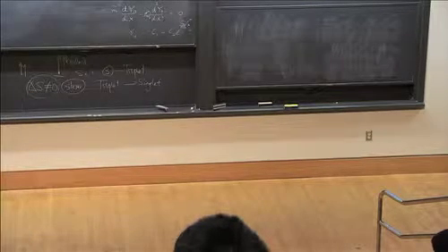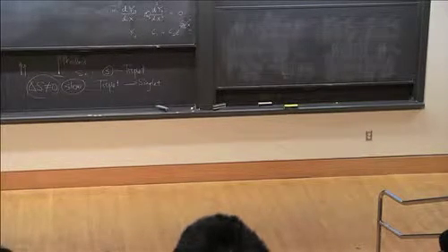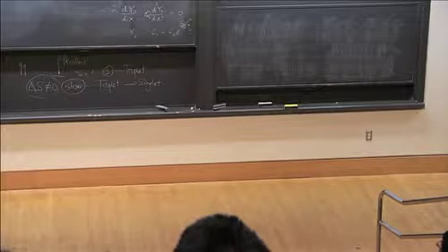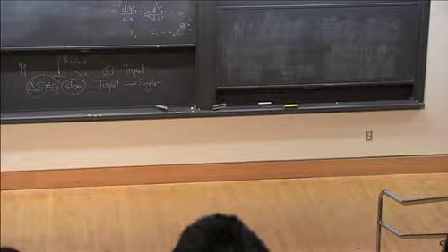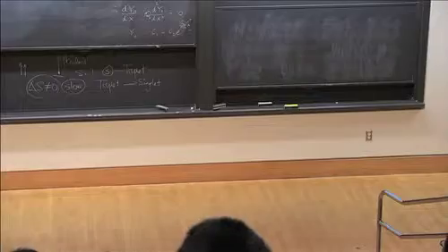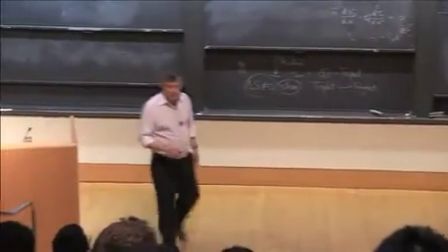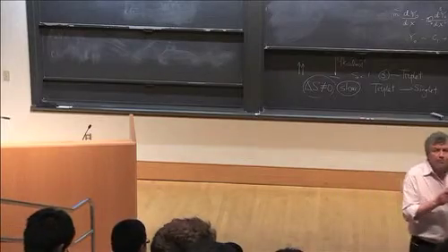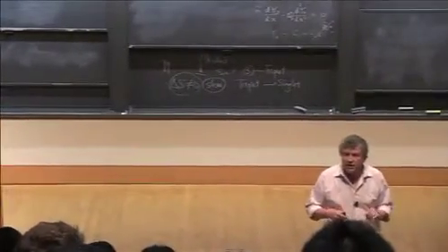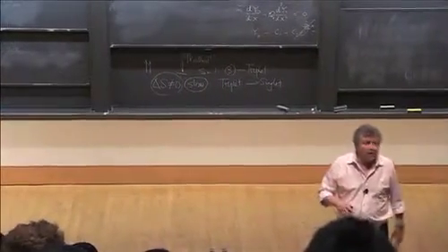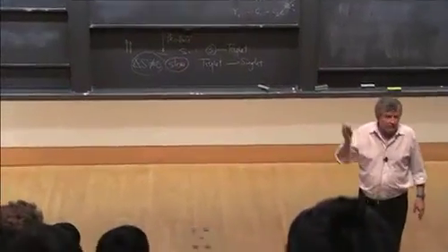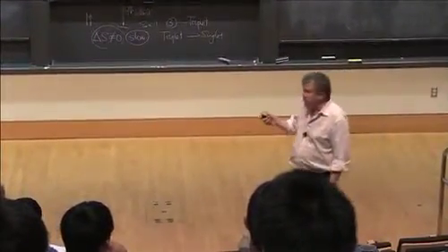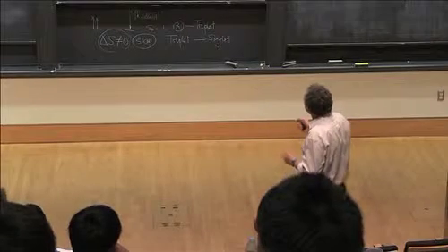Then we clearly cannot use the coupling function approach. But we can construct some jump relations across the reaction sheet, something like what we tried to do in premixed flames. Of course, it's different because of the nature of the problem. The diffusion flames are different.